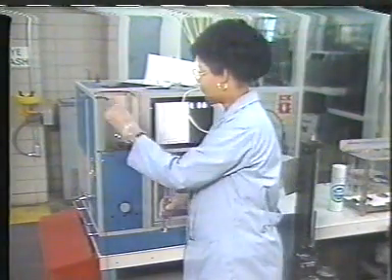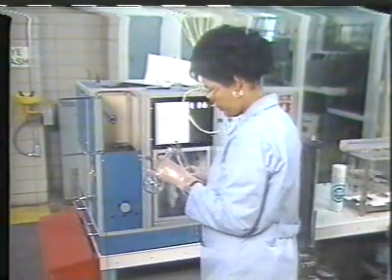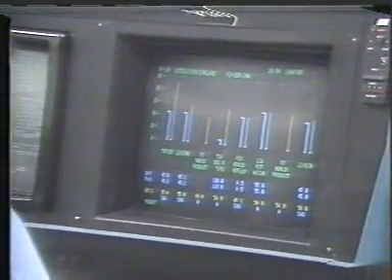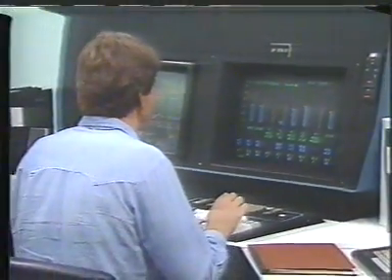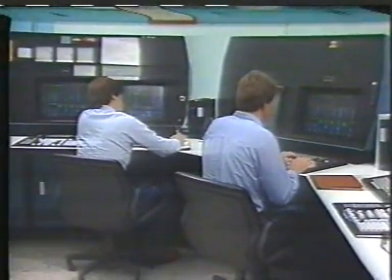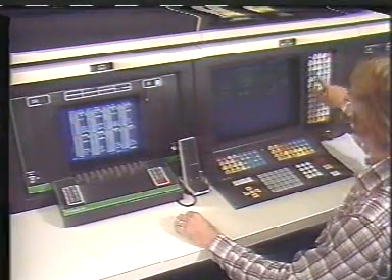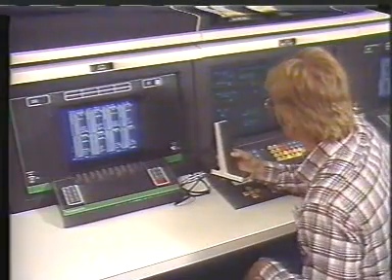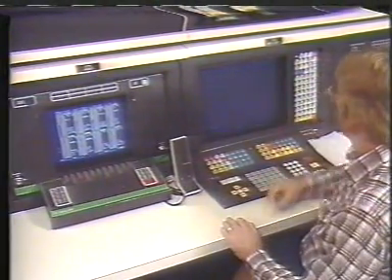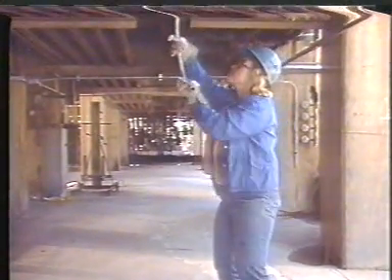An operator's primary job is to control the distillation process so that the products produced will meet specifications. While most process variables are controlled automatically by control loop instruments, it is the operator who is responsible for adjusting these instruments so that they accomplish the job they are designed to do. During normal operations, an operator usually makes minor adjustments to the heats and material balance to keep the tower producing on-specification products. Most of these cut point changes are made by adjusting the reboiler or furnace temperature or by changing the reflux rates. Product rates are then adjusted to maintain the desired material balance.